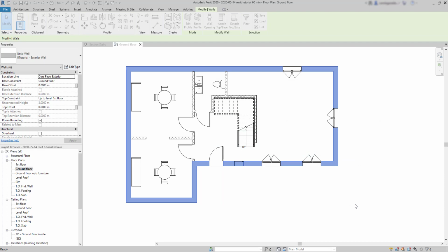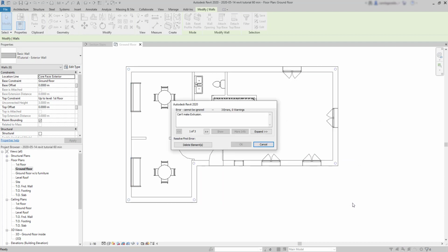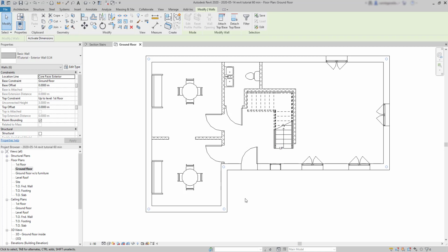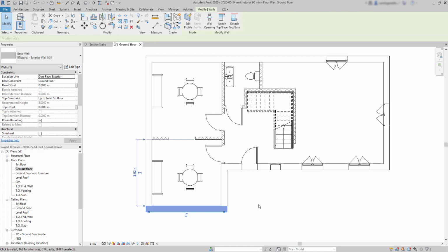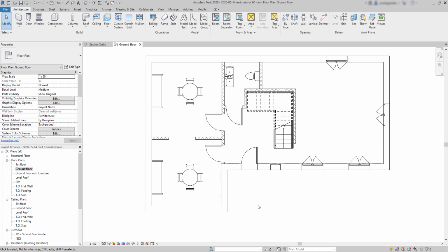But yes, be careful when you try to modify walls in an existing floor plan, as you may get some problems. Here you can see the notification. The wall expanded a bit inside, and some joints are no longer in the same position, as well as the sofas that are no longer aligned with the wall. Basically, the best is, before drawing the walls, make sure that you set a width you think you won't need to change later, and you avoid these dimensioning problems.